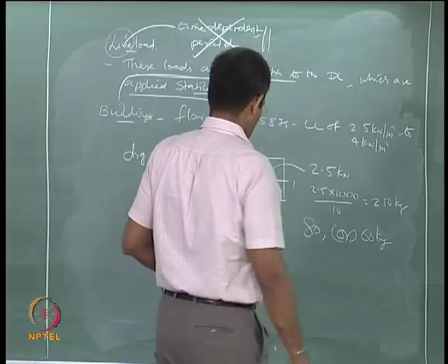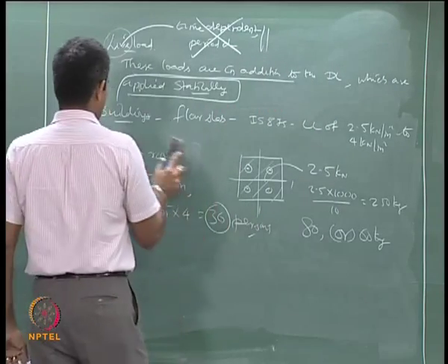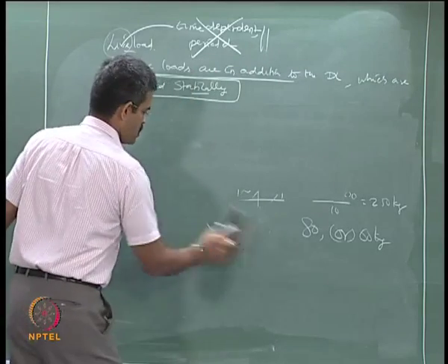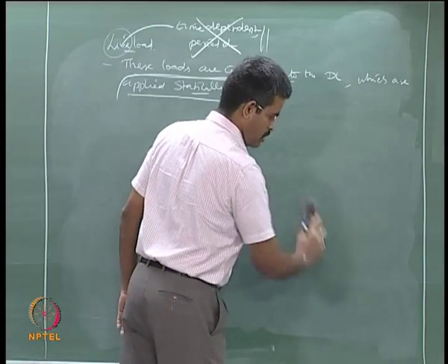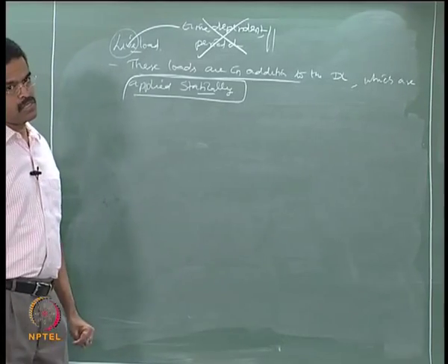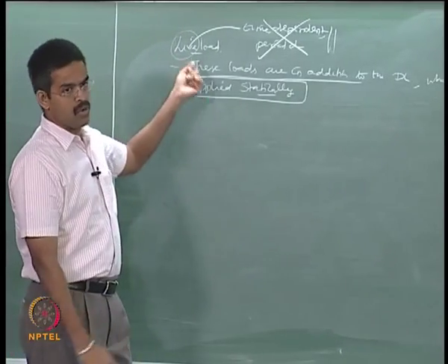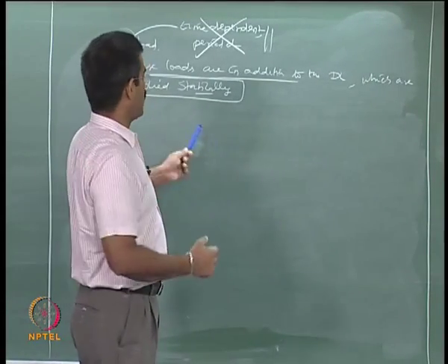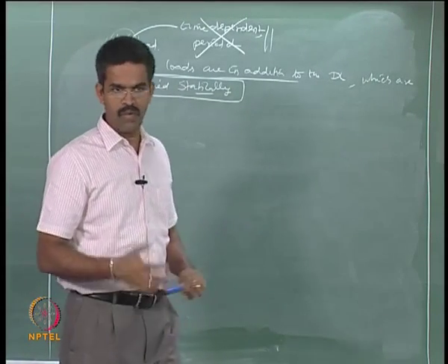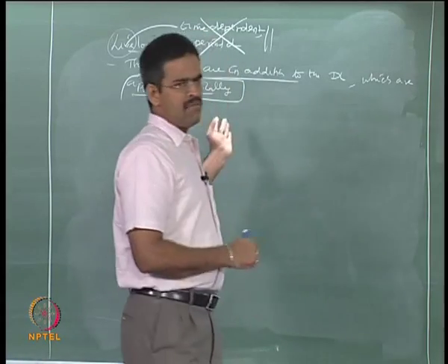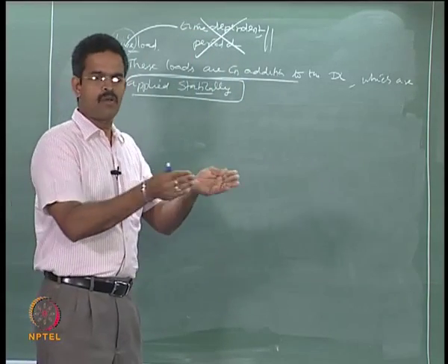Okay. So, we obviously cannot apply the live load suggested by building codes onto offshore structures, because we have a different concept. It is also a structure, but our operational loads in terms of live load are different. So, in our case, where do the live loads come from? For example, in a house, live loads come from human beings, etc. But here we have only a very limited number of people operating on the deck, isn't it?